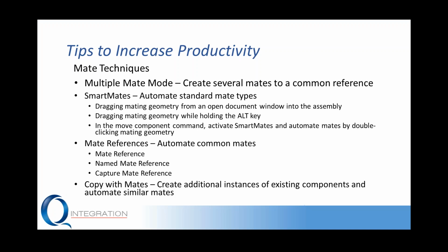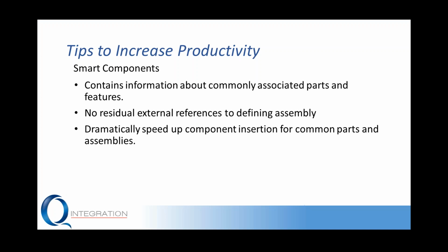So we took a look at some different mate techniques to help us increase our productivity from day-to-day work. Now I want to show you guys smart components. So what's really beneficial about smart components is this contains more information than just the part itself or the assembly, because we could also have a smart assembly. And so we can bring over additional components, we can bring over features into this assembly when we insert that component. And what's really nice about this is there's no external reference to the defining assembly for these smart components. And it dramatically speeds up the insertion process for some of these common parts that we have.